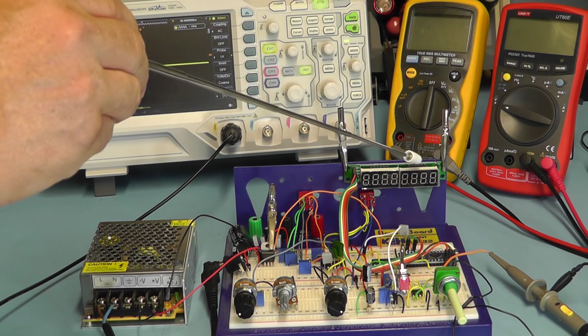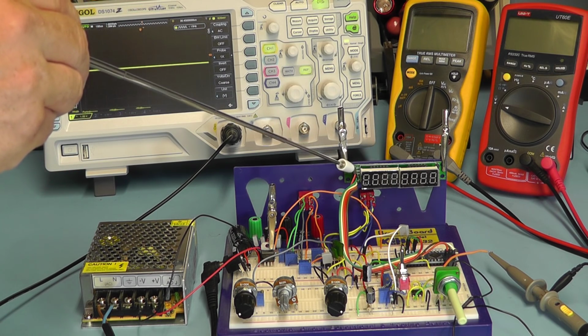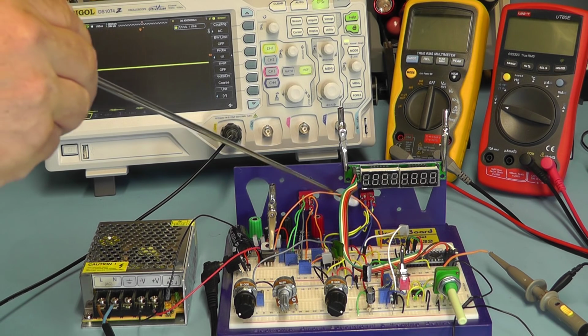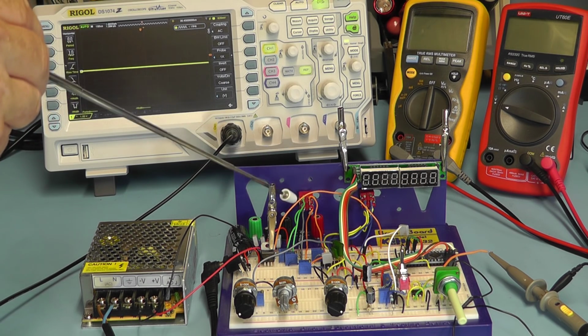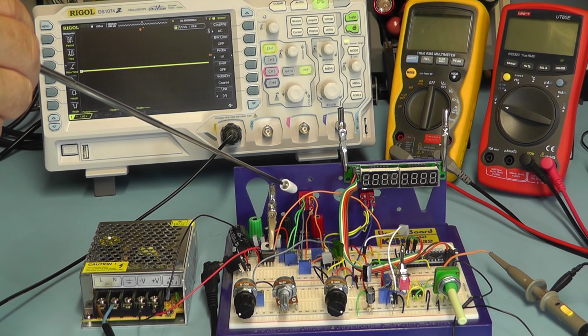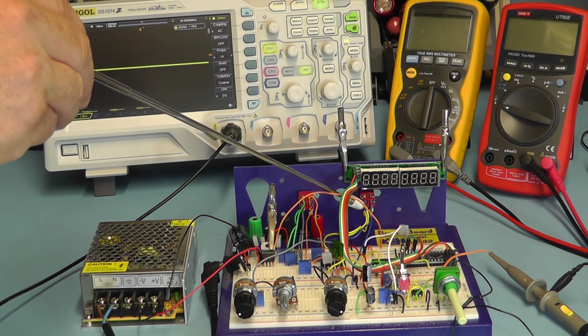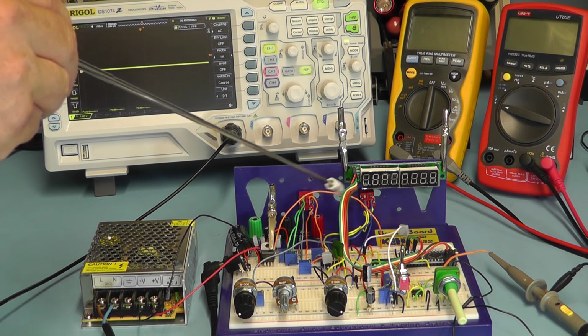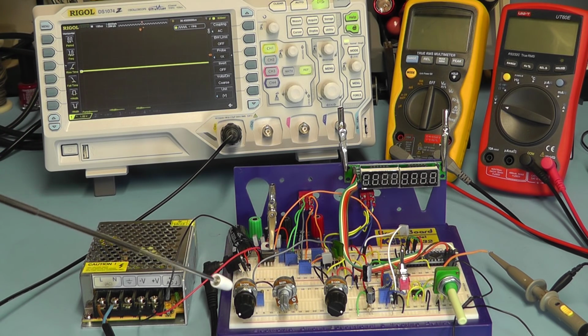I've just clipped the display on the back of this breadboard here so we can see it, and we have two switches positioned there. This one here will switch between the triangular and sine wave, and the other switch will switch from square wave to pulse mode. At the front of the breadboard I have the frequency control, and I decided to put a smaller value potentiometer in series with it to give us some fine tune of the frequency.